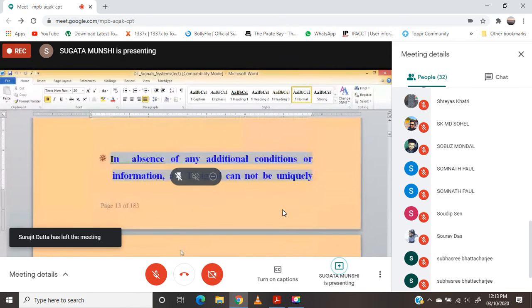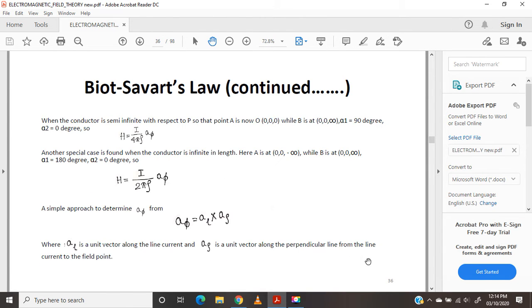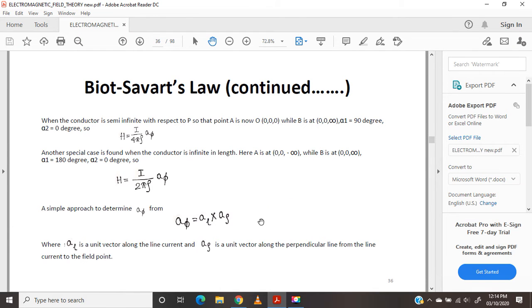So these blue, red, and green signals you will never be able to get back from the sampled signal, because when you carry out mathematical interpolation, these undulations or oscillations, rapid changes in between 2 adjacent samples, that information is not available to the mathematical interpolator. So the signal that you will get back from the samples will be the one with least possible oscillation. Apparently, it is this black signal. So this is the signal obtained by mathematical interpolation.